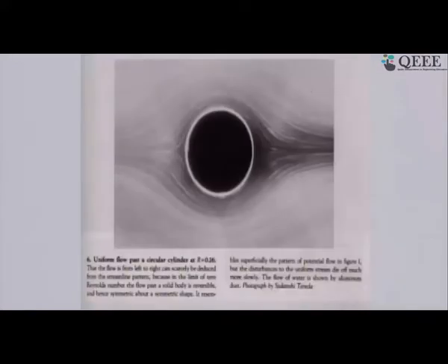Now let's see what happens as the Reynolds number increases, and here it is increased very slightly, and Reynolds number is 0.16. And again, this is a flow visualization done in an experiment by putting something in it and taking a photograph of it. So what you now see is that at slightly higher Reynolds number, the flow in the front part looks pretty much the same as what it was there. It has come here, it is bent, it's getting closer to the surface, the streamlines here are getting closer to the surface, and then it is going off back again.